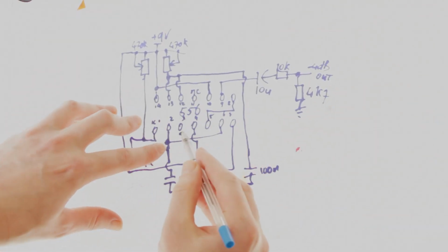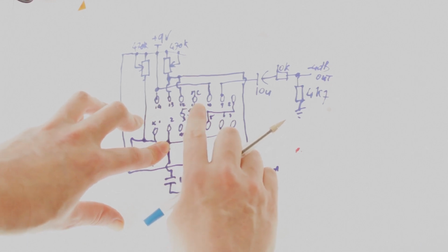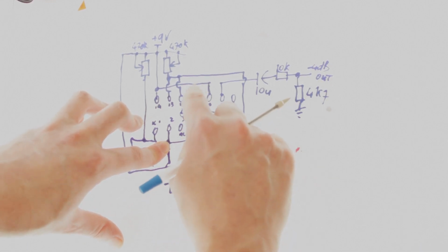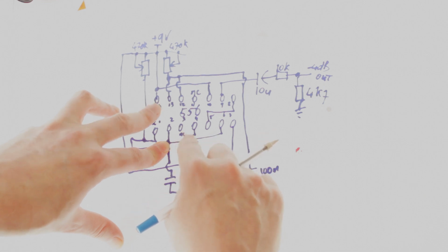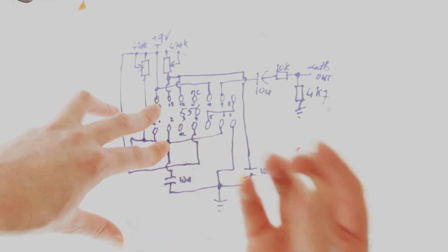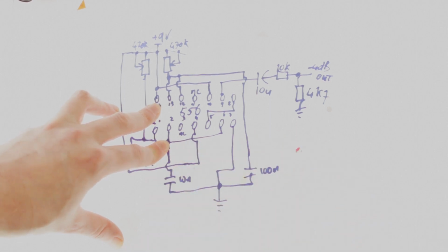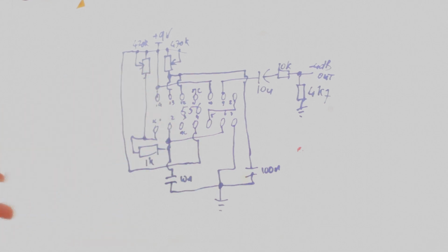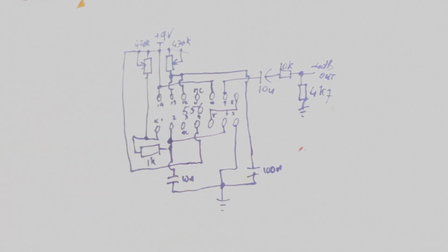So pin 3 and pin 11 have no connection on the schematic, but instead of just not connecting them at all, what I will do is take that off the chip and just add in a connecting point for it, because it might be useful for any sort of future expansions. If you want to have access to that pin, it makes sense to just have a connection point for it. So just look here, there is the pin, and then I can just put in a connection point.